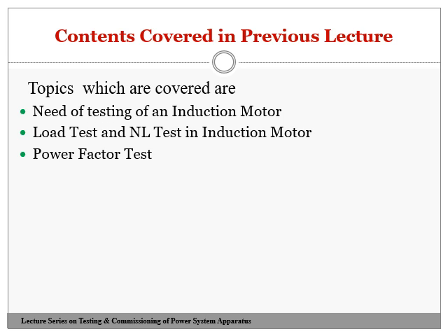Afterwards, we have seen the load test that is conducted on the induction motor as per the standards given by the manufacturer as well as the Indian Standards. In that test, we try to determine the efficiency, the slip and the torque at which the particular induction motor will be operating at different load conditions.